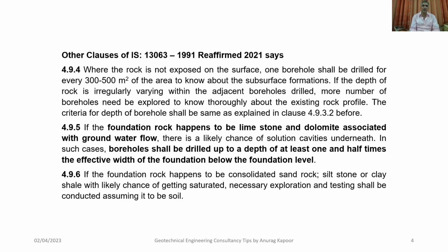And the last clause, 4.9.6 of this code, in reference to the boreholes to be drilled at the site for buildings resting on shallow foundations in rocky terrain, suggests that if the foundation rock happens to be consolidated sand rock, siltstone or clay shale with likely chance of getting saturated, necessary exploration and testing shall be conducted, assuming it to be soil, and then the reference codes which I have already discussed in my previous lectures are to be referred to in this case.